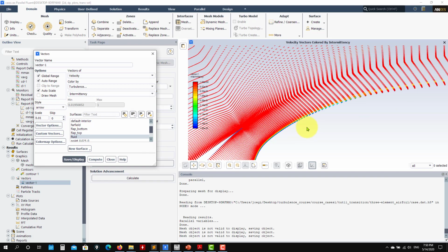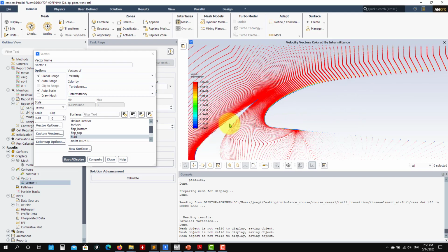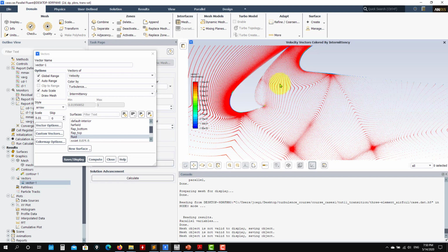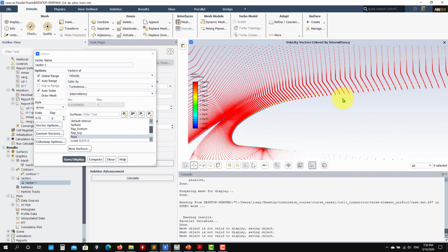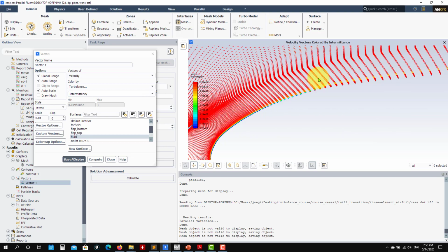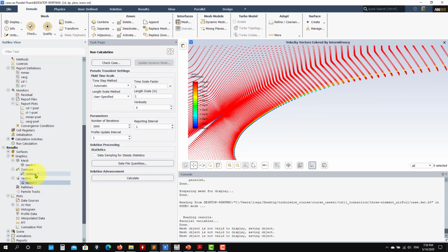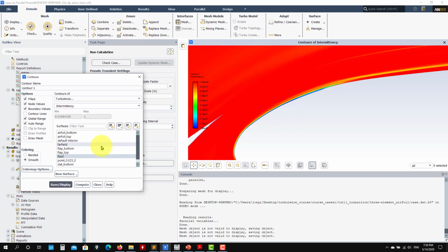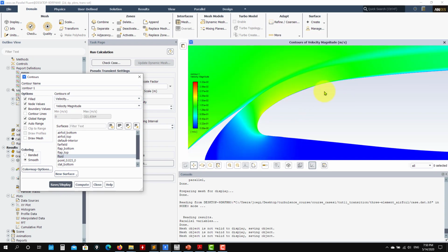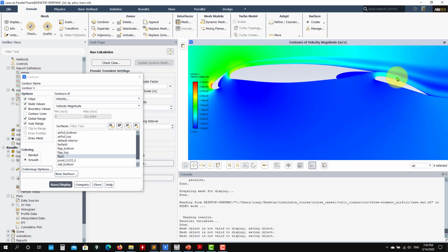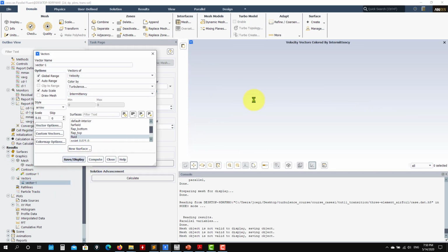And just to mention, maybe it is smaller, or you see that you didn't have that large bubble, because here you have a secondary flow entering. Remember that the flow is coming at an angle and passing here, and then that flow will have an influence here that will help this flow stay attached. So you see here, if I plot the velocity, you have this jet here that will reduce that bubble intensity. And also you can capture the other one here in the back. So let me go on and plot it again here.